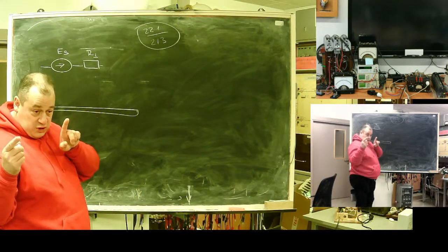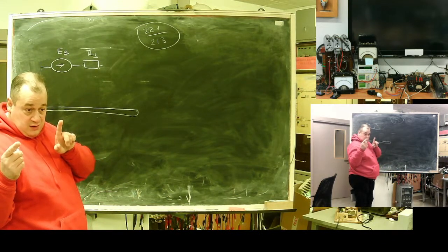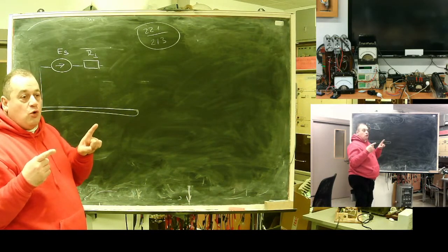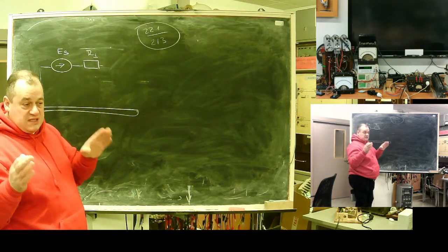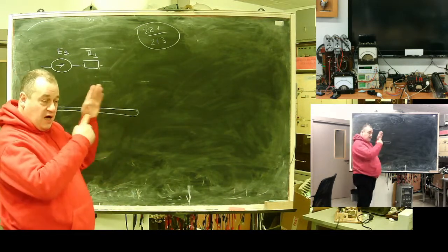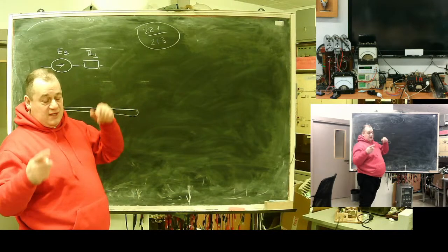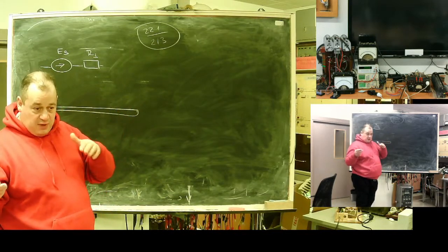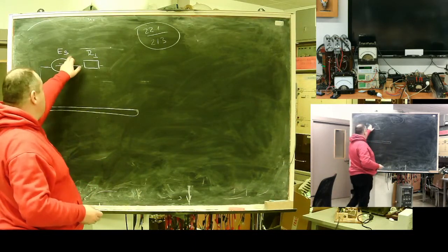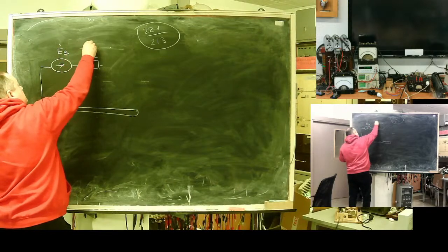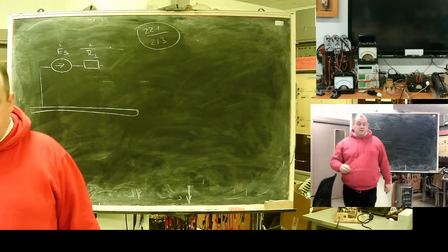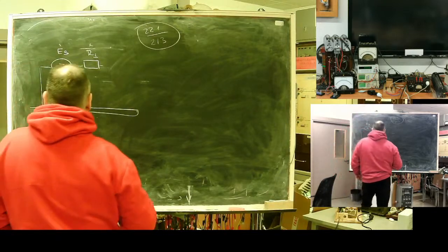You have two voltage levels or two voltage areas, 0.4 and 10, 11, whatever the distribution is. Maybe 24. If you decide to use 24 as a base, it remains intact and 0.4 goes up. Or you reduce 24 to 0.4 and the schematic will be at 0.4. So these, I will mark them with a star, but they will need reduction to the base voltage. What else?